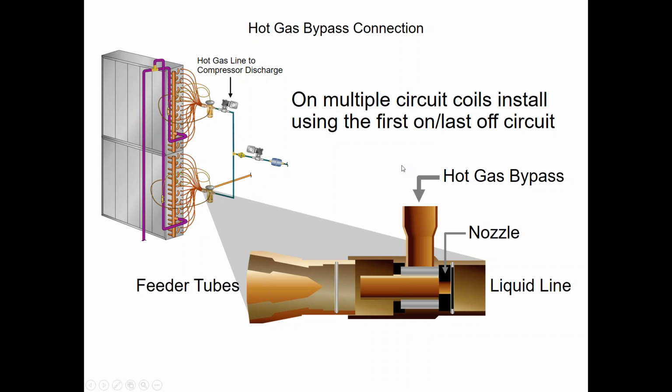Right. And some compressors have oil in them, meaning like an oil sump. So all of your hermetic scroll compressors will have an oil sump and a volume of oil in it, varying from multiple ounces to 64 ounces or less. Semi-hermetic compressors, reciprocating, have an oil sump in them.